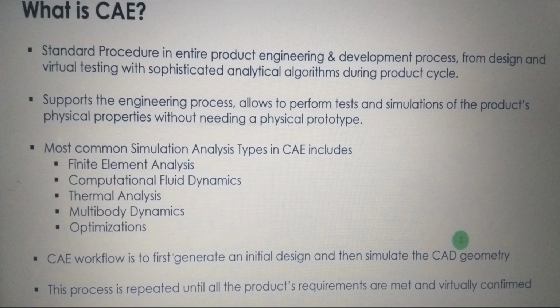So what am I supposed to do? I get into optimization of the L bracket. How can optimization be done? I can improve the performance of the L bracket by adding thickness to it. Imagine it's a 1 mm thick bracket. I can increase the thickness to 2 mm, after which it will have extra strength to hold the 10 kg object that is going to hang on it forever.